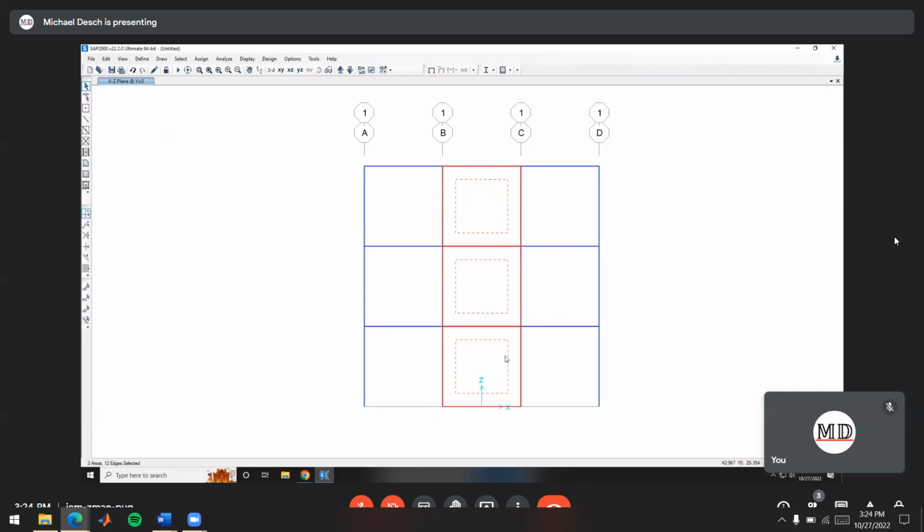and it'll give us a better result. Now this works up to a point because adding more pieces adds more computational complexity to the model, and we don't want to give it like a billion pieces because it'll take all night to run. So we like to find ourselves a nice optimum middle ground here. For this lab, so it doesn't take forever, we're just going to do a 2 foot by 2 foot mesh. In reality, you'd probably want it a little finer than that, but it's fine for our purposes here. Any questions?